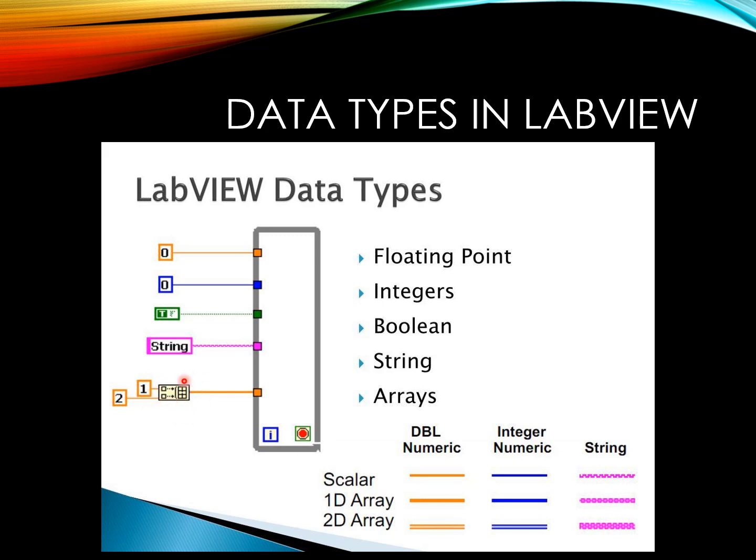And here is the array. See, array is the collection of data which can be numerical or Boolean or string. So such facilities are available in a cluster. That cluster is nothing but a data type which provides combinations of things. So in numerical data also, you can process only scalars, or you can do one dimensional arrays, or multi-dimensional arrays are also possibly handled. So such quality data types are supported by LabVIEW.